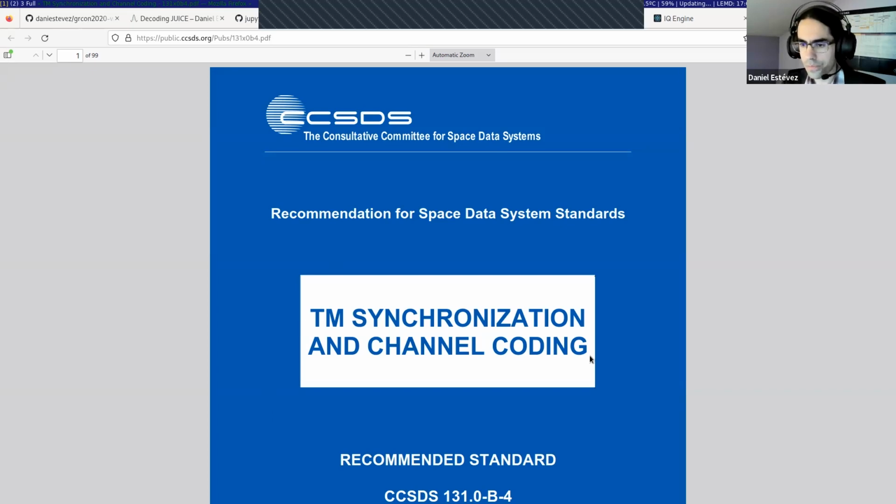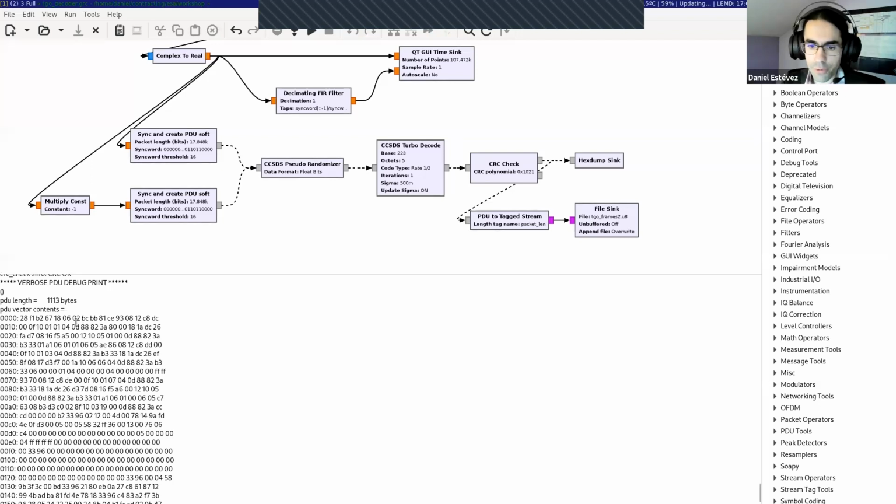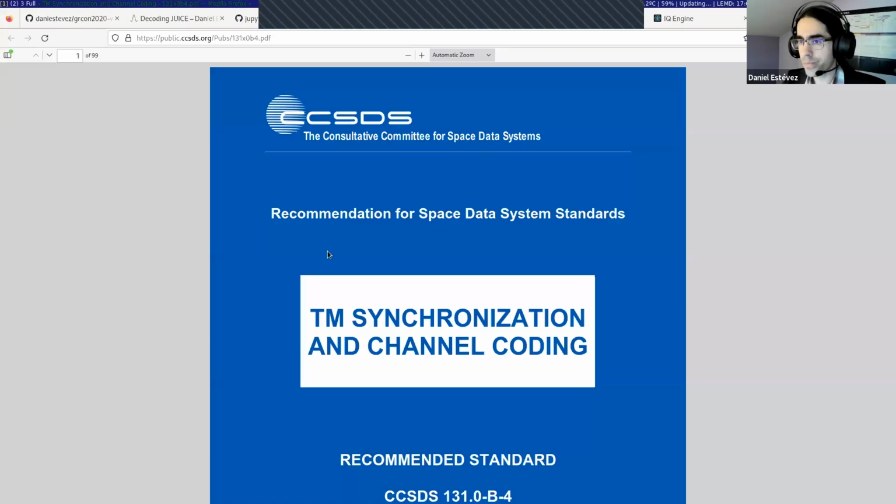So that's basically the format of these frames, and the first bytes are a header, which tells you the spacecraft identifier, which points to a particular number used by TGO. Where data begins here, what's the virtual channel, and useful data goes in a virtual channel. Idle data goes in a different virtual channel so that they can be easily separated at the receiver.